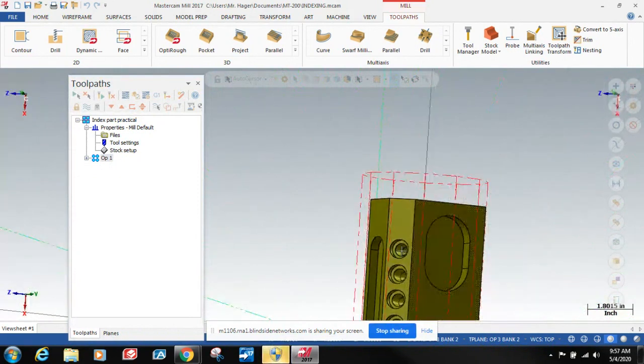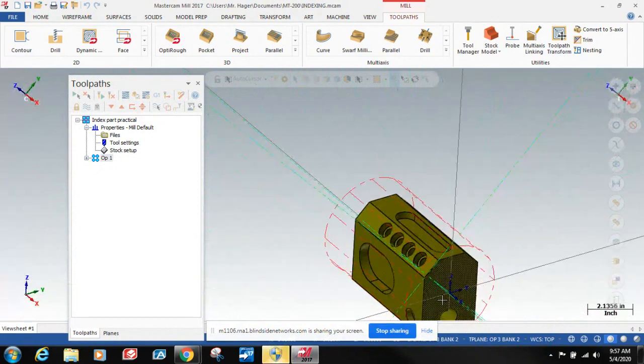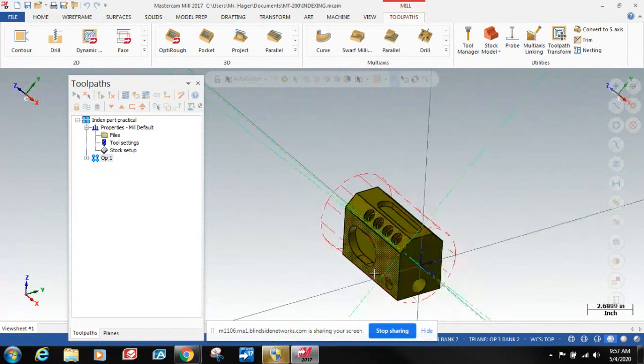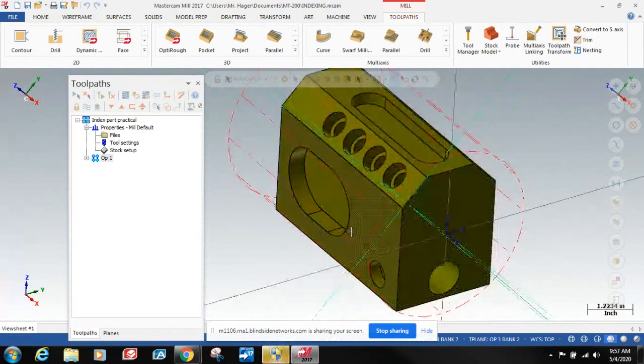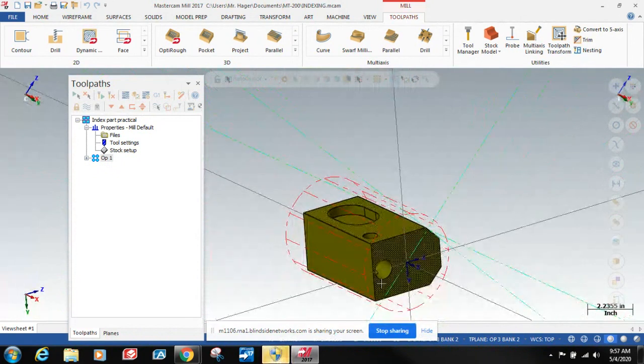We do all of those sides, and then we should end mill the front here with a long tool. You might do it in this position so you don't need too much length, square that out.